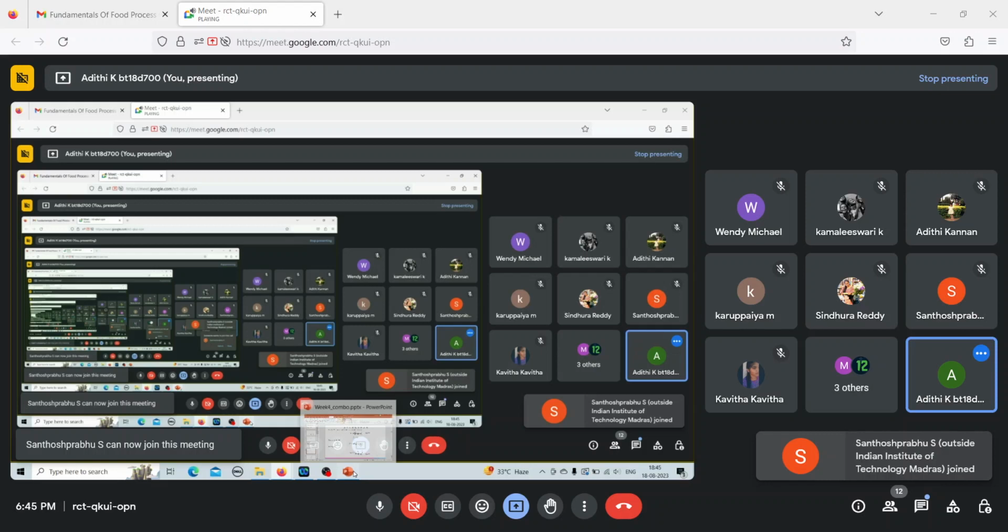So you have three streams: you have F, you have L, you have V. So 242 kg per hour of water is basically the V that is given here. That is the water that is coming out of the evaporator in the form of vapor. So the total mass balance is F is equal to L plus V. And the mass balance for the solids is F into XF is equal to L into XP.